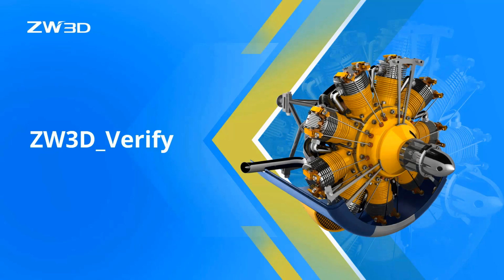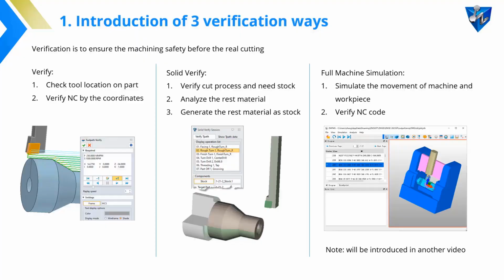In this video, we will learn about the basic verification ways in the ZW3D CAM module. As we all know, safety plays an important role in CNC machining. Before we put the NC code to a real machine, we need to check the toolpath and ensure the safety. There are three ways to do the verification: verify, solid verify, and full machine simulation.